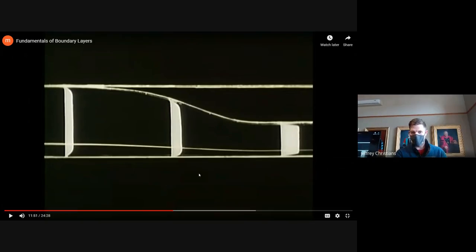So we see that a little bit. You can see the streamline too. You can see it goes from being, say, that far away from the wall to being half as far, which again would tell us that the flow rate between that streamline and the wall stays constant, so velocity goes up. You can also see, like here, the fluid is moving relatively slow next to the wall. Pressure is pushing us down this contraction. So down here near the wall, everything is moving pretty fast.